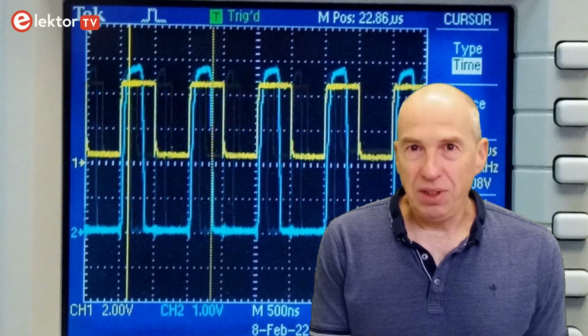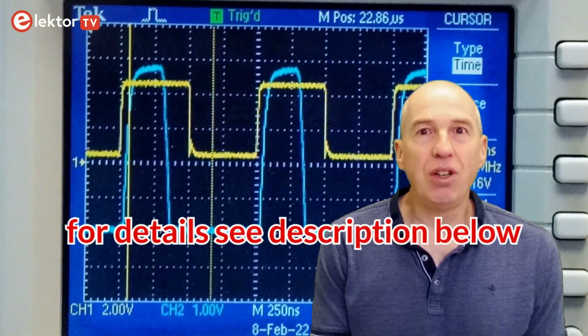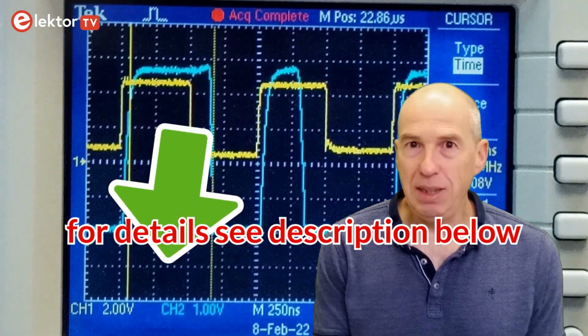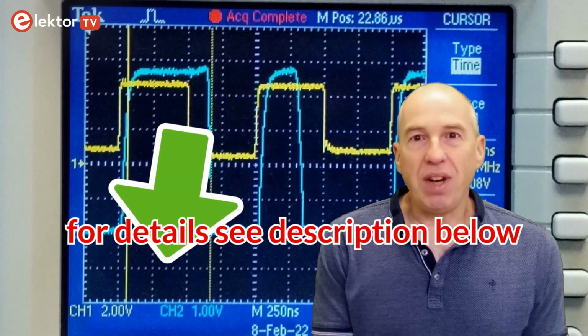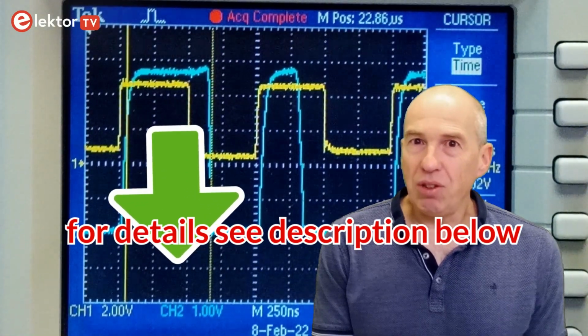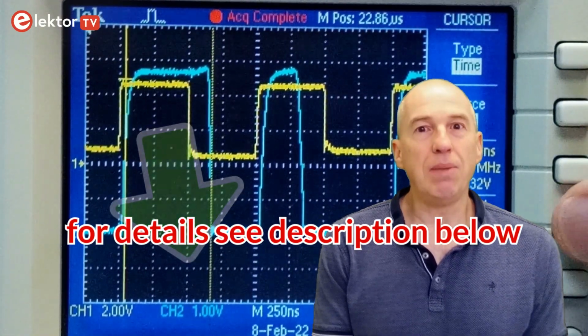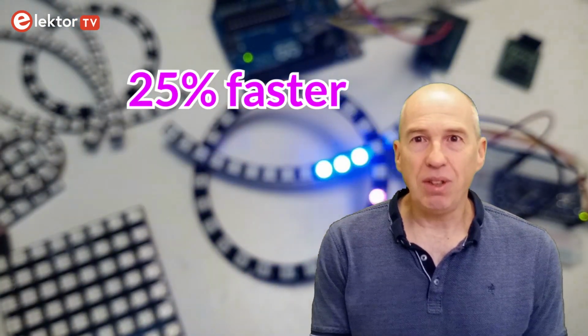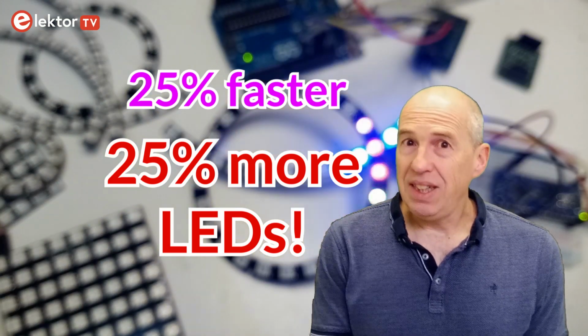Summarizing, with the circuits presented in this video, you can turn any SPI port capable of running at 1 MHz into a WS2812B type addressable RGB LED port. This allows to simplify the driver software and therefore it leaves more resources available for the rest of the program. Also, it is 25% faster than a standard 800 kHz driver, so you can drive more LEDs in the same time.